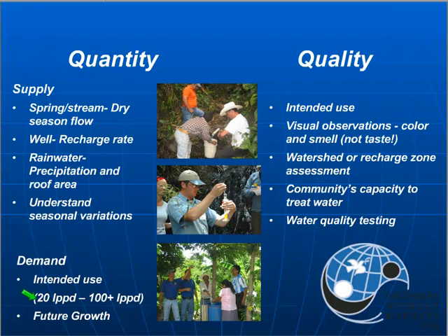And so what you find, I think I've worked on or done reviews for projects in dry areas of Kenya where this value is used because the community would never dream of using the water from this system for anything beyond just drinking and cooking. Versus, gosh, in Honduras where I was, this was the expectation because that was one of the main reasons for a water supply system, is that women didn't have to walk far to do laundry in these streams or access points that were far away. And so getting that water closer, assuming that there was a source that was enough, was important, and so that needed to be what that per person demand was. So it just depends on your community.